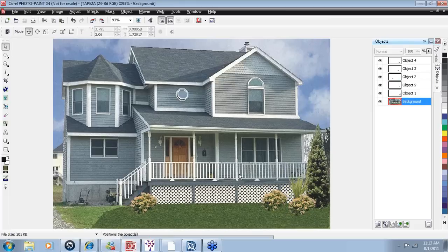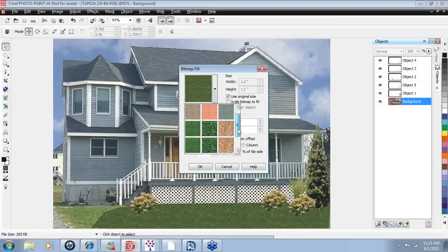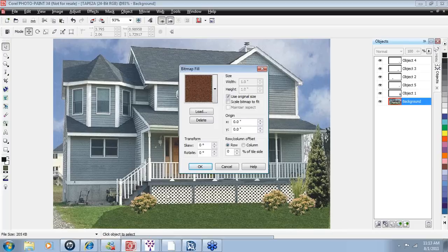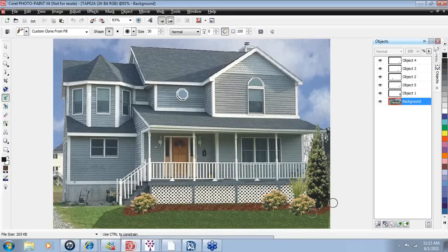One of the features that I think is a great time saver is the ability to add on your mulch, paint it on. And you can paint on your mulch at any time of the design process. So I went back into our textures, changed the grass to a mulch. And now I'm going to select our texture tool. This does give you the ability to change your paintbrush shape as well as the size. But you'll notice that I can paint directly over top of my objects. That mulch goes right down to the base layer.